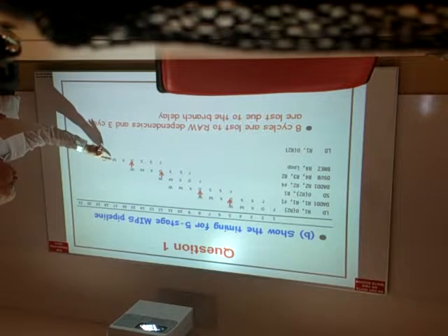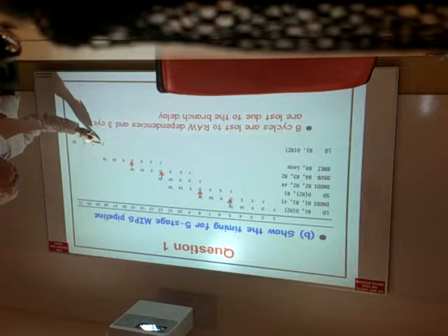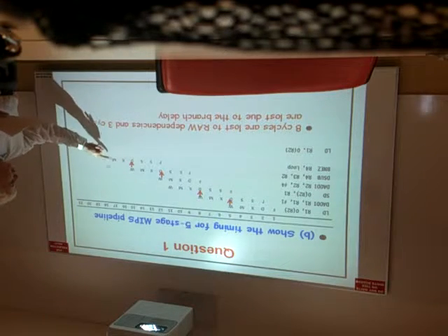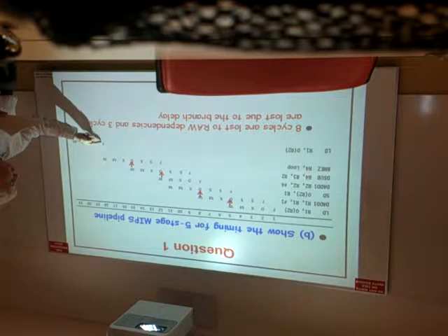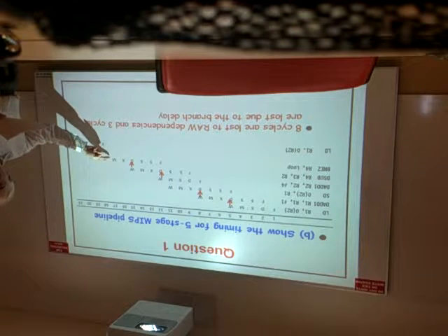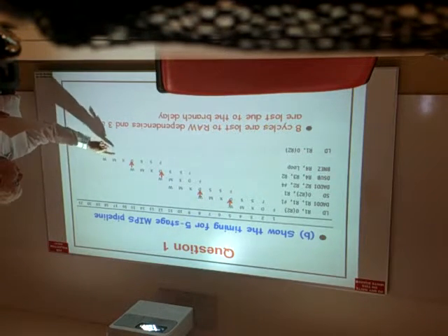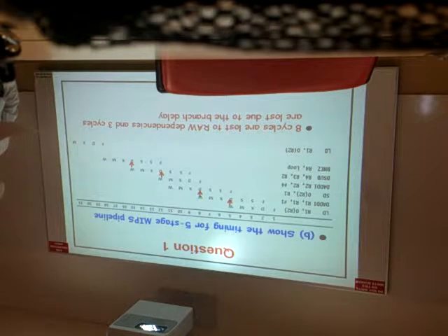So when we take the branch, we will lose 3 cycles because we can't fetch the next instruction until we've updated the program counter. So we lose 3 cycles due to the branch delay.